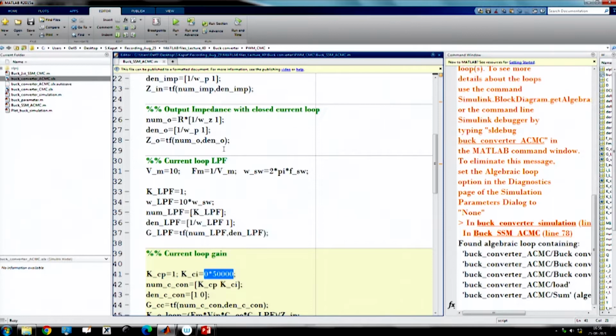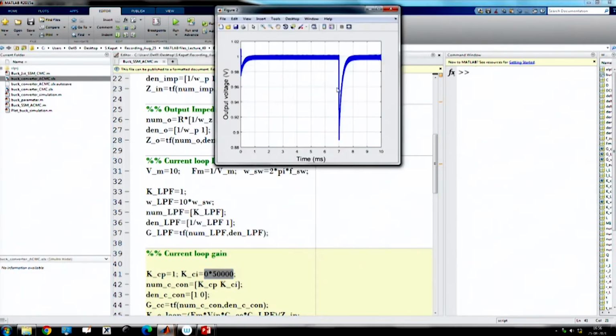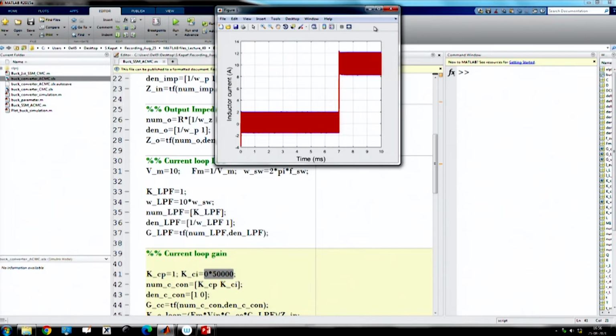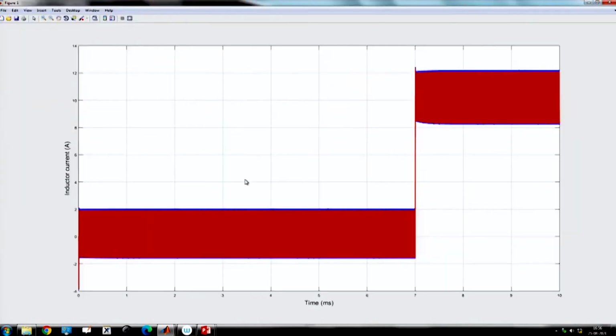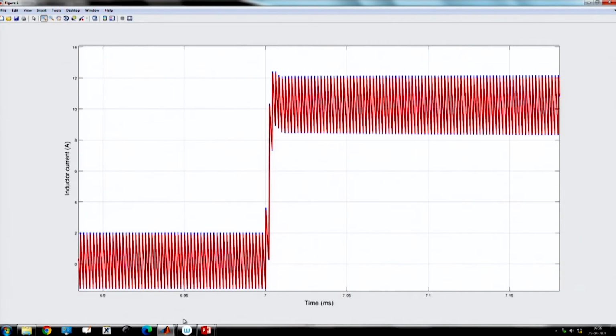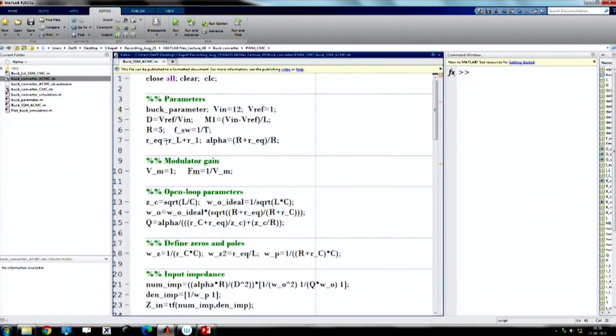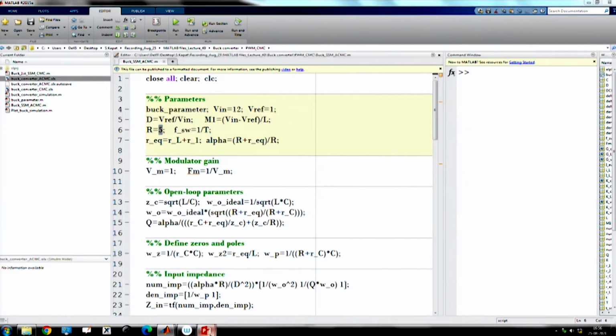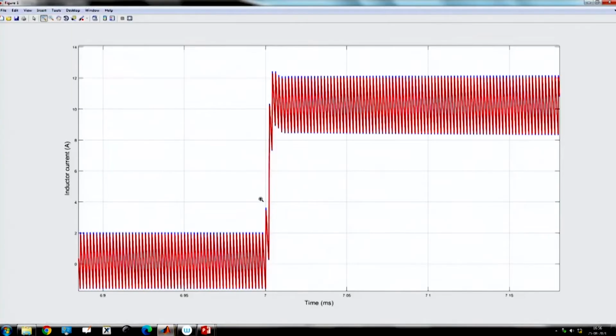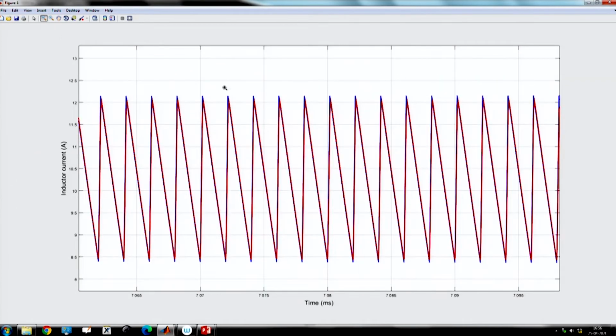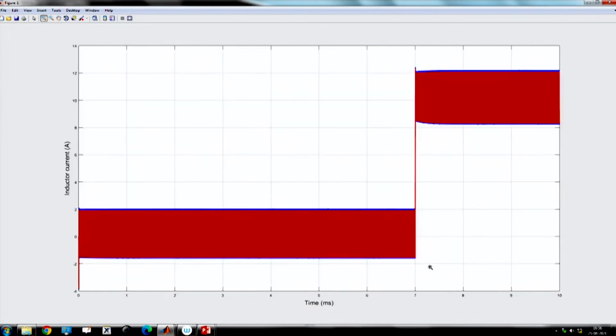what the response of the system is when we choose such a setting. So, here we have given a 10 ampere load step. Okay. The initial load current was very low, I can tell you that the initial load resistance was set to 5 ohm. So, 1 volt by 5 ohm is 200 milliampere, right. So, it is changing from 0.2 ampere to 10.2 ampere. Okay. Now, what are we going to show here?